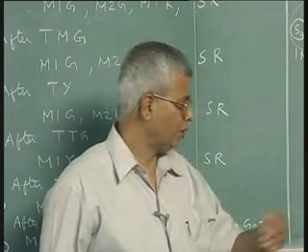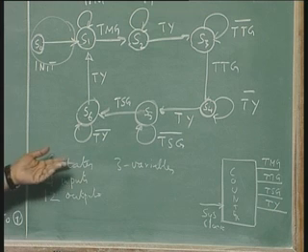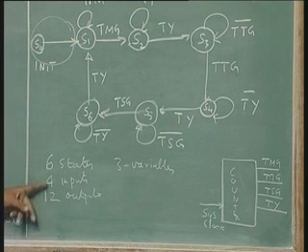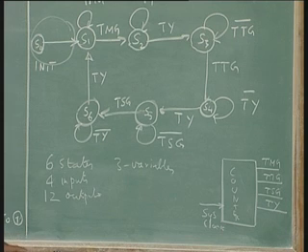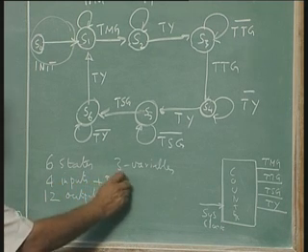Sometimes there is no need to have separate signals, you can have the same signal going to 2 different lights if one is the complement of the other. But I am not taking all that into account right now. Right now I am looking at the bare state graph, saying there are 4 inputs, 12 outputs, 6 states. 6 states requires 3 variables, that means 4 input variables plus 3 state variables.